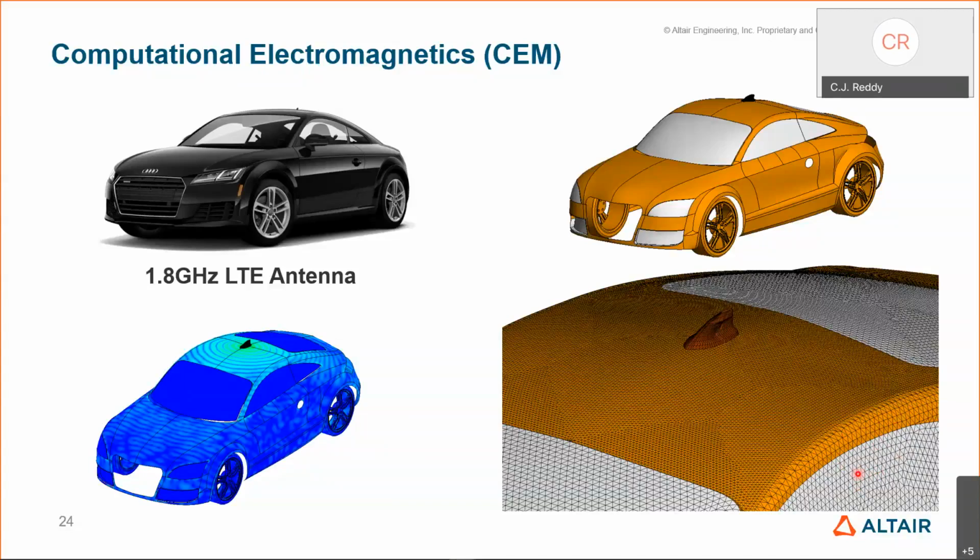What that means is that as you go to higher frequencies, the wavelength decreases, so your triangle size decreases, so the number of triangles you have on an object increases, which means that your computational cost, that is the memory required, but also the time required, increases. So that's where the solutions come into the picture, in terms of FEM or FDTD or method of moments and other kinds of solutions.